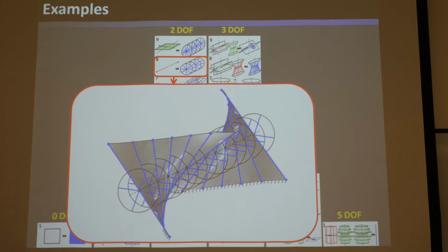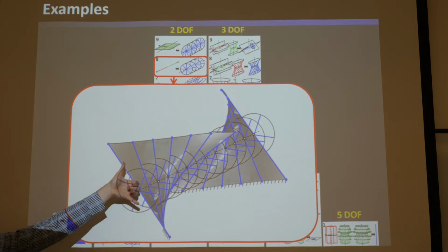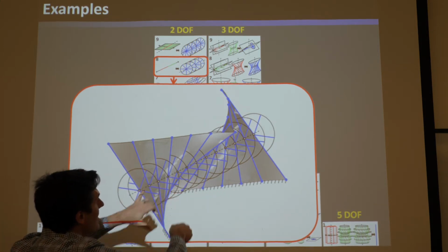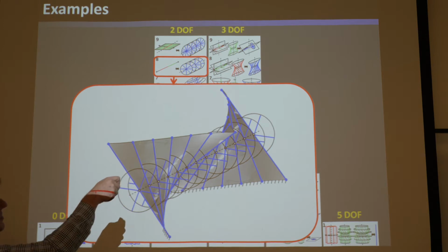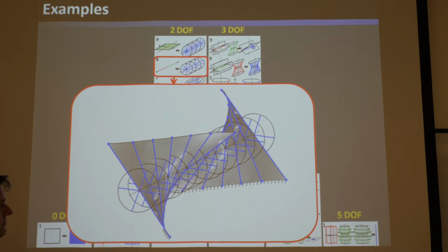element that's going to work better if you rotate this way and then stop here at this crease and then rotate back. Okay, but you didn't have to. You could have rotated it at a rate that's not consistent with that. So anything that's not a hyperbolic paraboloid that rotates as it translates will lie within this constraint space. Okay, and we'll have this freedom space. And we'll have an order of constraint, by the way, of 4 instead of 3, like this hyperbolic paraboloid.